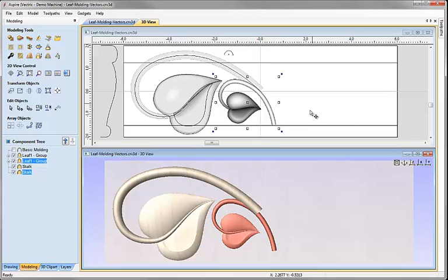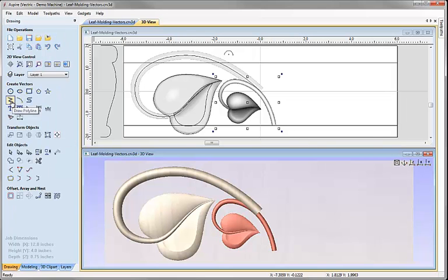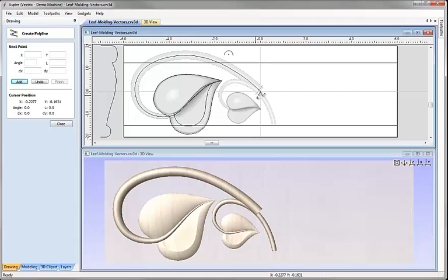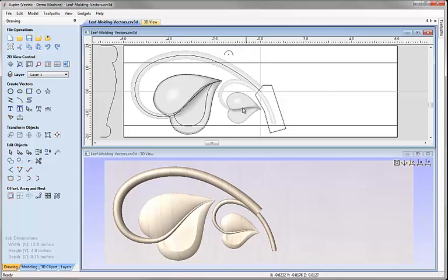Happy with that. But what I want to do is just trim off the excess here. I don't want this part of the stalk coming past here. So I'm going to click on the drawing tab. I'm going to click on the draw polyline tool. I'm just going to sketch across here and down and around here. Just close that off, right mouse click to accept it.